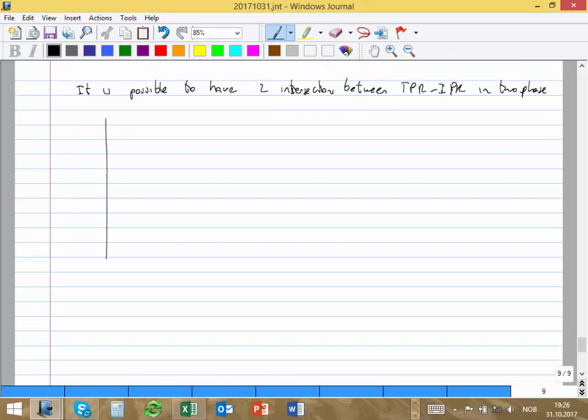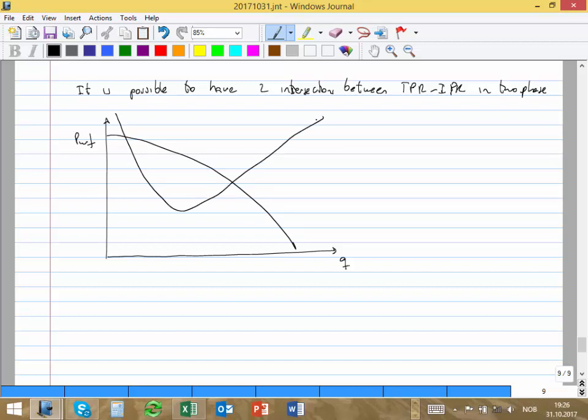So if you see now, I painted intentionally, that's Q and that's PWF, and my curve will look like that. And what happens if my TPR is like this now? That's my TPR and that's my IPR. I have two intersection points. So which one is the well going to choose? We want the well to be here, right? That's what we like. But really nature may choose to be there. We don't know.